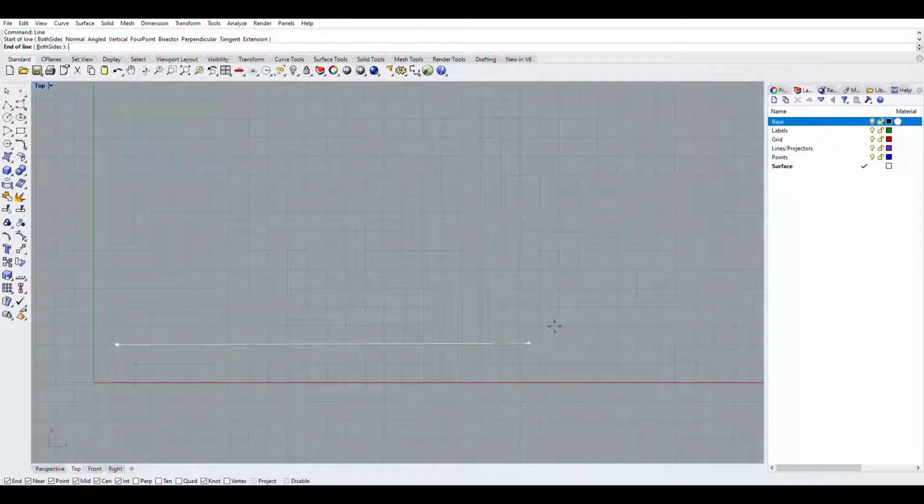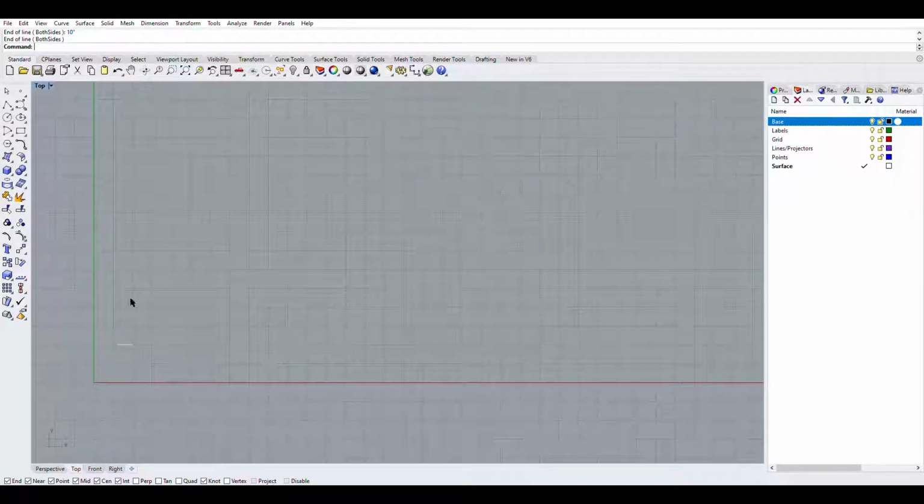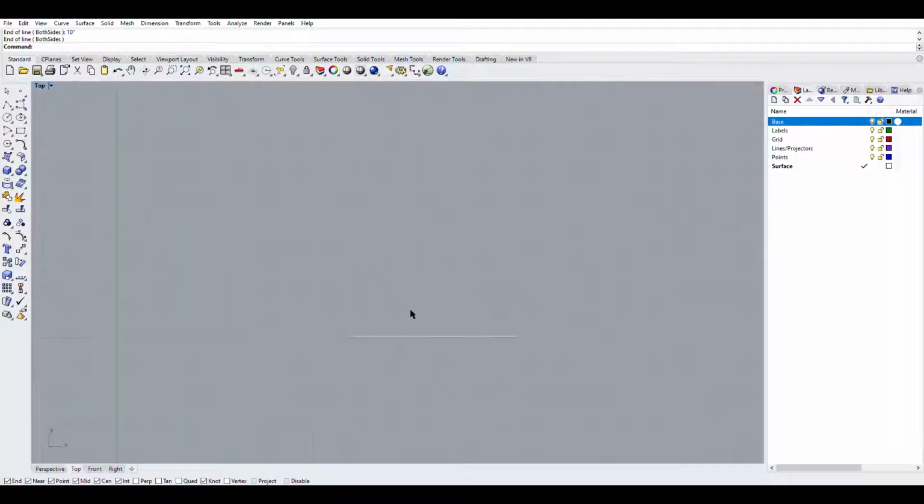I typically don't change anything in this kind of format. So I'm just going to drag my first point and type in, let's just do 10 inches. So now I have a 10-inch line. I can hold shift and press enter. And you can type in 10 IN for inches, or you can do 10 and then your quotes. Double quotes is inch, one quote is going to be for feet.